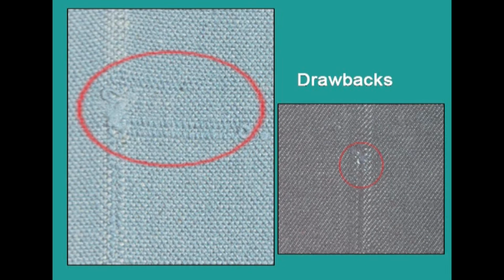And drawbacks, this is caused by excessive loom tension gradually applied by some abnormal restriction. When the restriction is removed, the excess slack is woven into the fabric. Usually the ends are broken at that particular point, and so it is considered as a major defect.